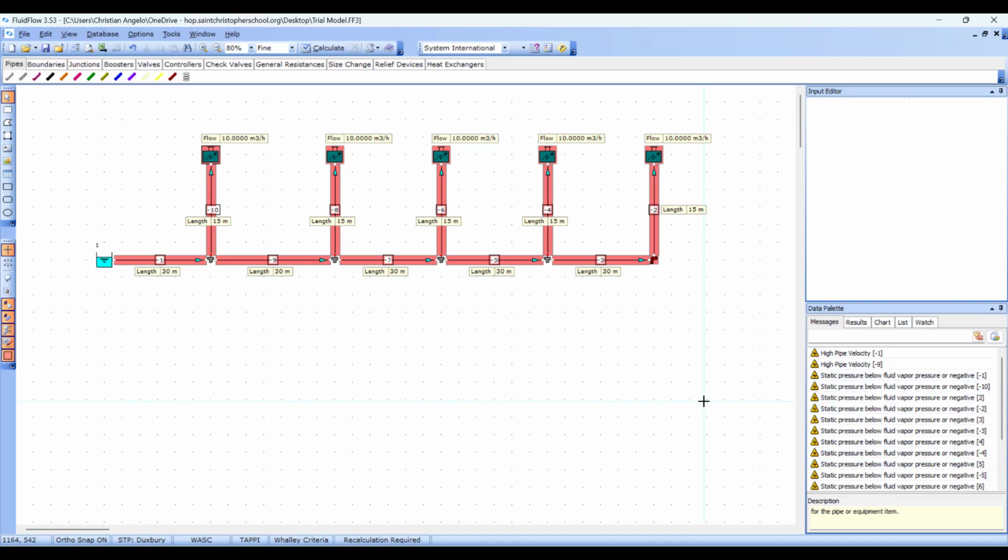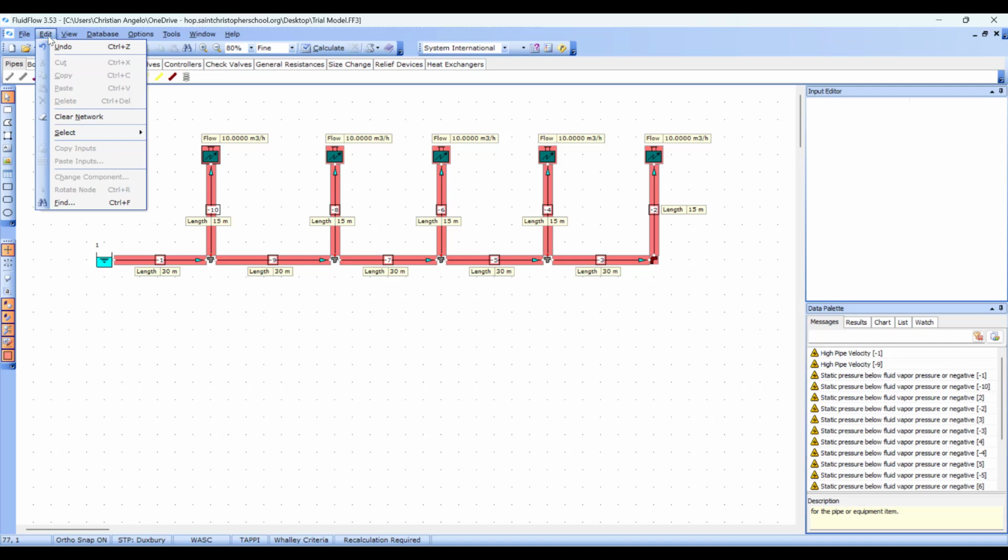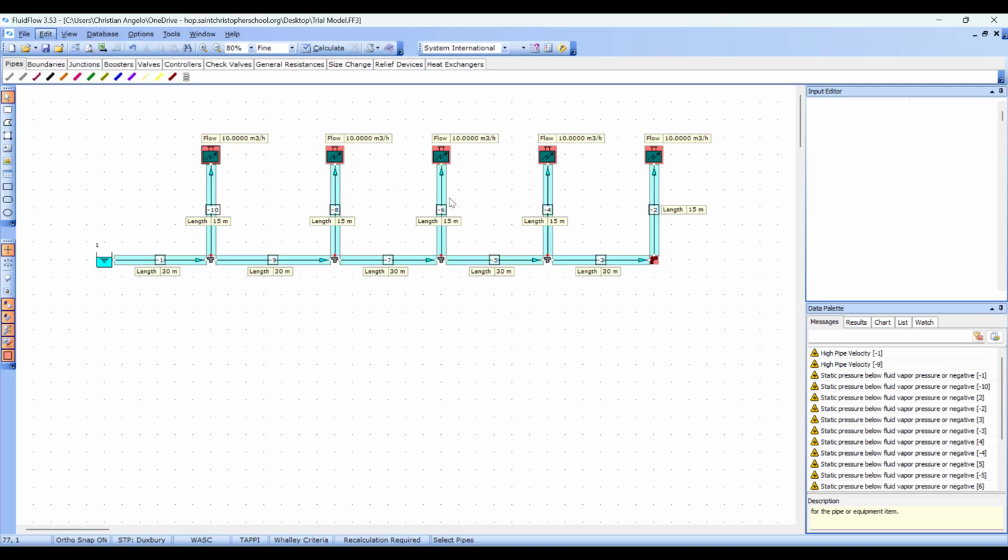For demonstration purposes, we will use economic velocity as our sizing model to determine the appropriate pipe size. This sizing model is the default setting for the pipe material we have applied. Using this information, we will replace the original pipe sizes with another standard size closer to the exact economic size identified. To make the replacement of pipe sizes easier, let's multi-select the pipes and show the economic size result on the flow sheet.